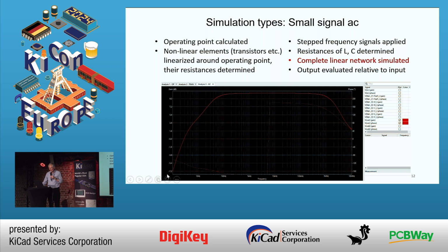This is a frequency sweep starting at 1 hertz, going up to 10 megahertz for this device. And you see there is some high pass behavior because of the emitter feedback circuit we have chosen for this tiny transistor amplifier. Then there is a flat top, from 100 hertz to a few hundred kilohertz.